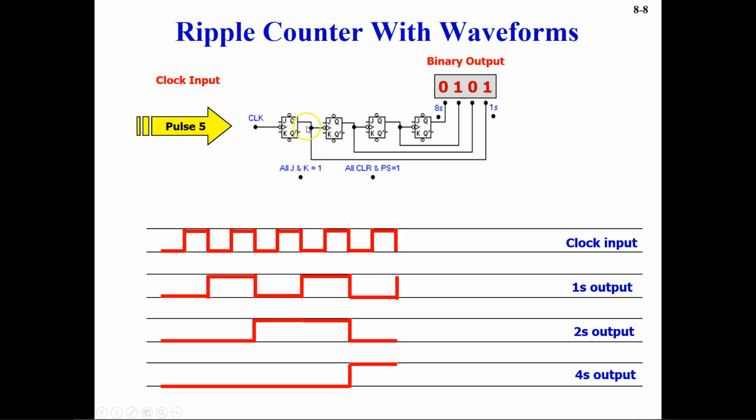And if you do not understand at this point how this is working, then you may need to go stage by stage. For example, when the first pulse is provided, what is the state of this flip-flop, and this flip-flop, and this flip-flop, which means at that first case, when your pulse 1 is provided, what is this Q, this Q, this Q, and what is going into the clocks at that pulse 1.